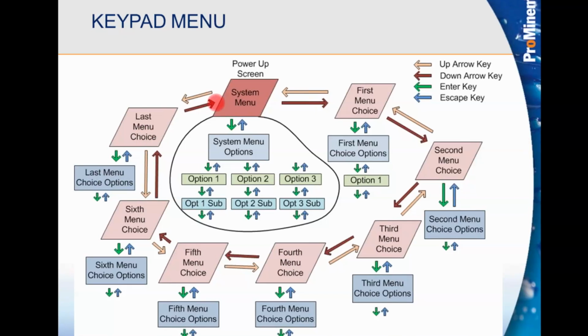The higher level controllers, like the Multiflex and the Aegis, allow for one complete loop. If you just press the up arrow only, the up arrow being this tan arrow, you would go backward through the menu. If you use the down arrow, you would go forward through the menu. And what will happen is you'll see all of the I/O points that are currently enabled in that controller.